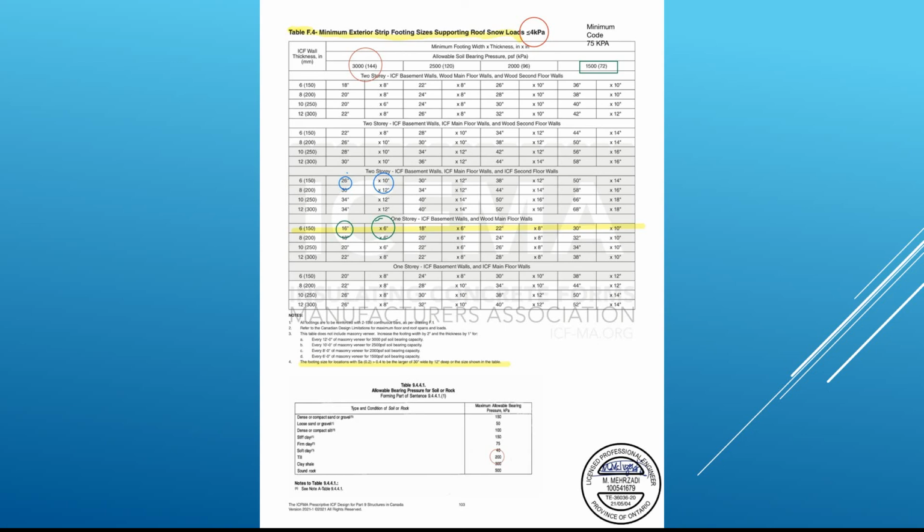Now, if you had a soils engineer, if you had some soils that were a little suspect, of course your soils engineer would be able to give you the allowable bearing pressure of that soil. But in most cases, as building inspectors, we'll go and look and say that we're looking for rock or stiff clay, but around here we generally use a till. So again, that's a little bit of a dance you have to make there. But any of these numbers here are well above the code. They'll get that straightened around, I imagine, at some point, right?